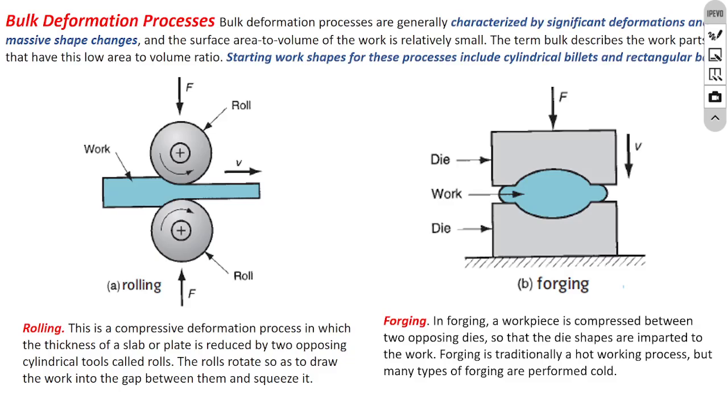Even we cannot find such a press machine to apply such an extremely great force. To be able to use a moderate size press and decrease the magnitude of the force to apply, the thing to do is to heat the material, and while the material is hot, shape it.